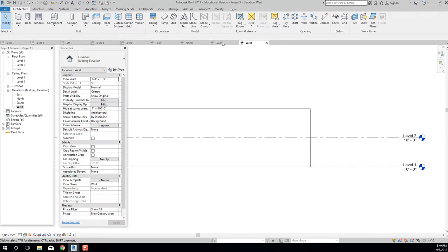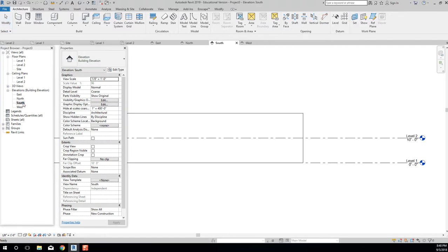And this is actually kind of a new and improved version of Revit. This was actually a really good improvement over 2018. The way that these used to function is that you would click and open up a view, and all the views that you previously had open would just stack invisibly behind the view you were on, right? What's nice about these tabs is that the same thing is happening, right? I have 1, 2, 3, 4, 5, 6, 7, 8, 9 views open, with the most recent one just being current.